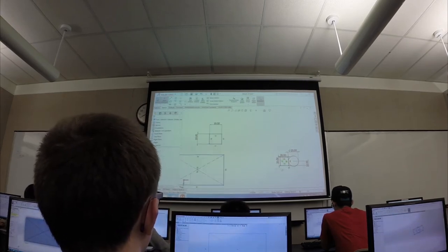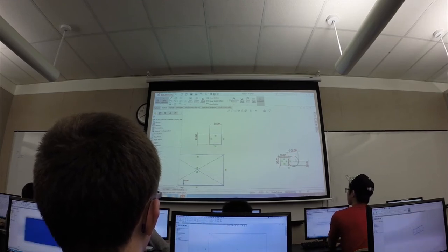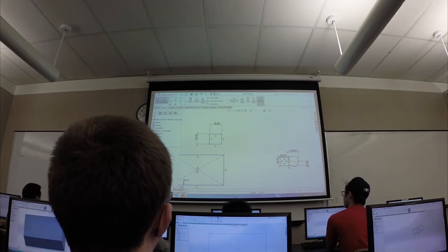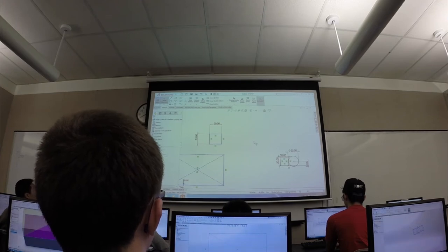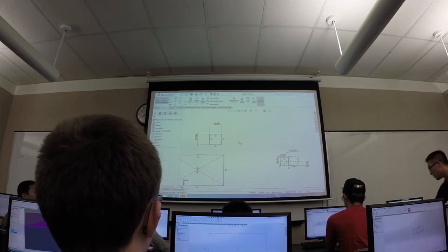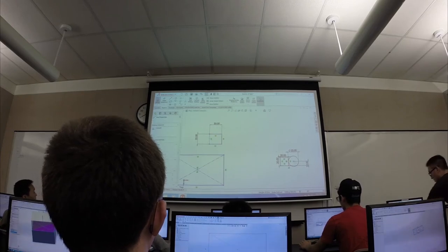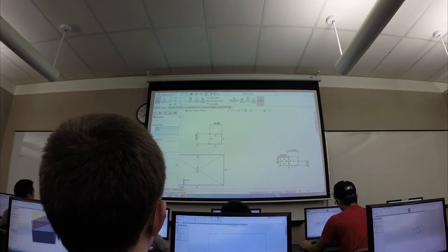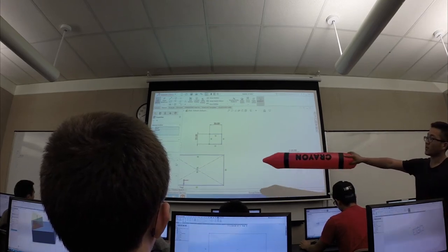Cool. And let's say we want this line to be running through the center of the circle, right? Coincident with this point here. So we would add a relationship between the two. There's several ways you could go about doing that. As we showed earlier, you could select a relation between the 2 points, like that.